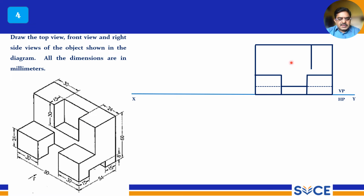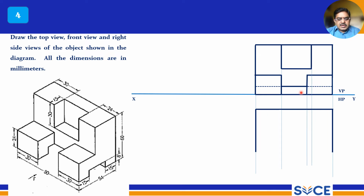Now this is 24 mm, and the height is 30 mm. So 24 mm and 30 mm should be drawn here. It is almost a straight line here, and there is an offset here. So it will look like this. And there the front view ends, and then you have to draw the top view.